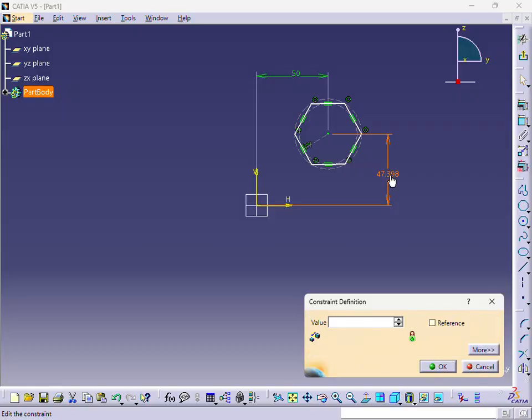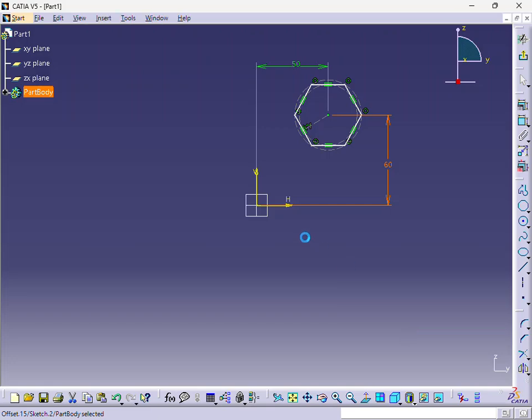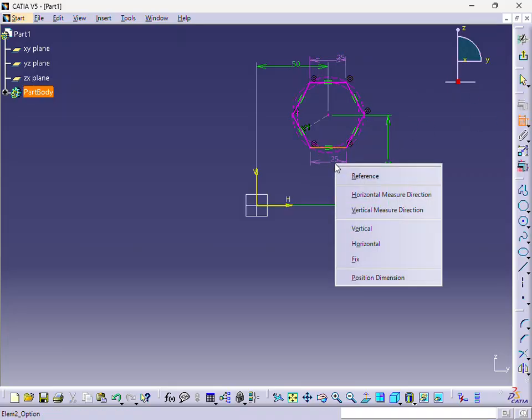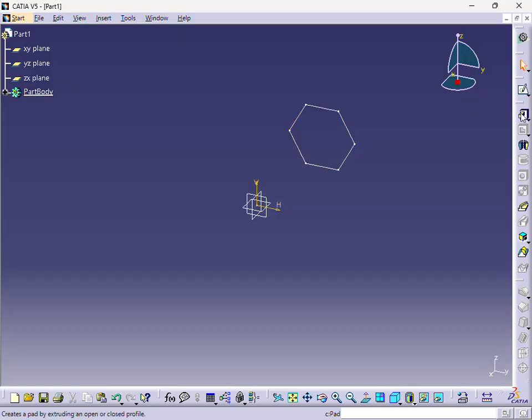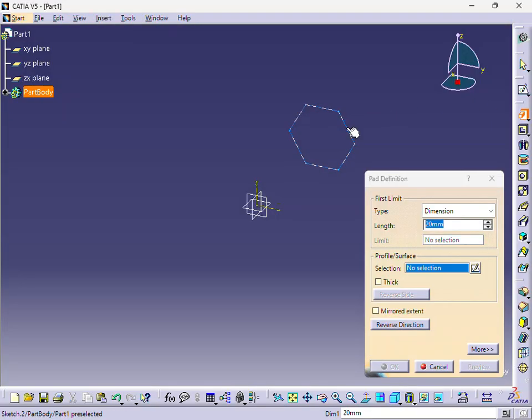Now, even though your vertical and horizontal axis went to a specific location, we can use them as references to help build our geometry and build our sketch. So we would constrain everything else here. I'm simply going to put a value here. We'll round it off to 25. And to keep it from rotating the whole thing, I'll make that horizontal. So everything's fully constrained.